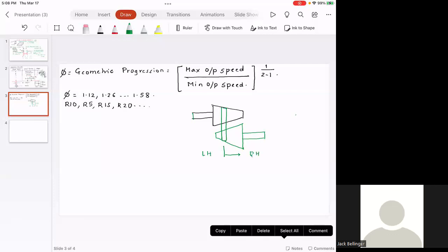So this is left and right. And as you can see, if there is input and there is output, depending upon where the belt is, your reduction ratio is different. Everyone understood this? So initially, think about it. If the belt is all the way towards the right, your input shaft is rotating at a high speed, but the output shaft is rotating at a low speed, which means something like you are in the first gear, you have high torque.